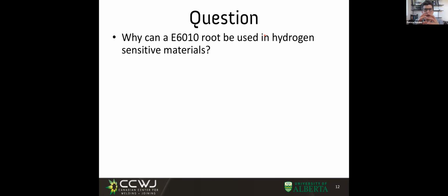And if you remember, the hot pass means a pass in which we deposit a bigger bead. And because it's a bigger bead of 70-18, that one doesn't have problems with hydrogen, will cool down relatively slowly. But most importantly, it's going to be heating up the previous layer of 60-10 and baking off the hydrogen that was in the 60-10. So if we didn't do the hot pass after the 60-10, we could have problems.